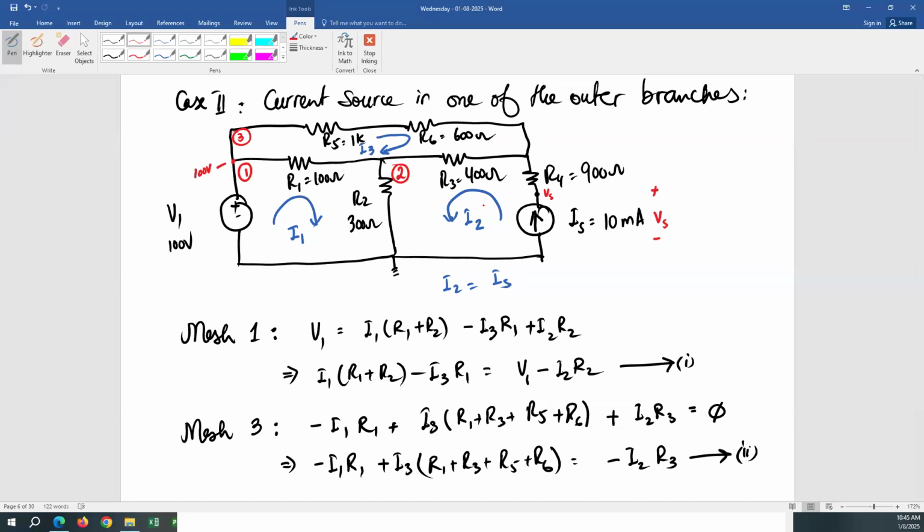Would it be really complicated to choose the node that's right above? You don't know the voltage at that node. What is the voltage at that node? You need to choose a node for which you know the voltage, because that's your initial value. Now, you always know the voltage of ground. You can always start from the ground.